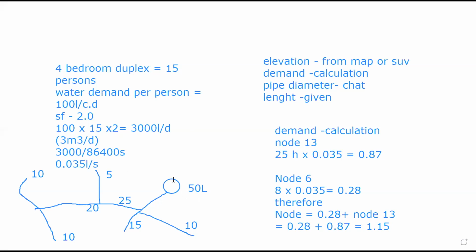So water comes here, 50 liters. It gets to this junction, it's still 50 liters. 10 liters flows here, 15 liters flows here. Definitely 25 liters will flow this way. As it gets here, 5 liters diverts, 20 liters will continue. So before you get these 20 liters, you must get 10 and 10. You get 20. Before you get 25, you must have gotten 5 and 20. That's exactly how to do this pipe network. This thing can be elongated as it's coming and branching off, and that's why you see pipe sizes increasing based on the population equivalent.